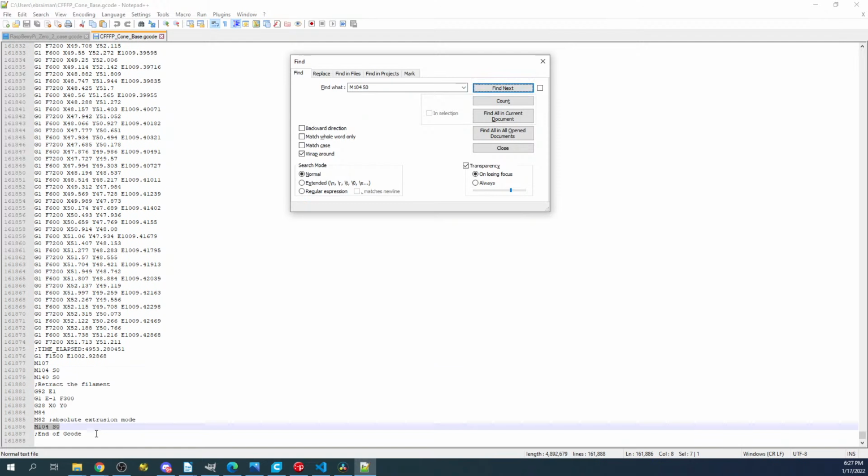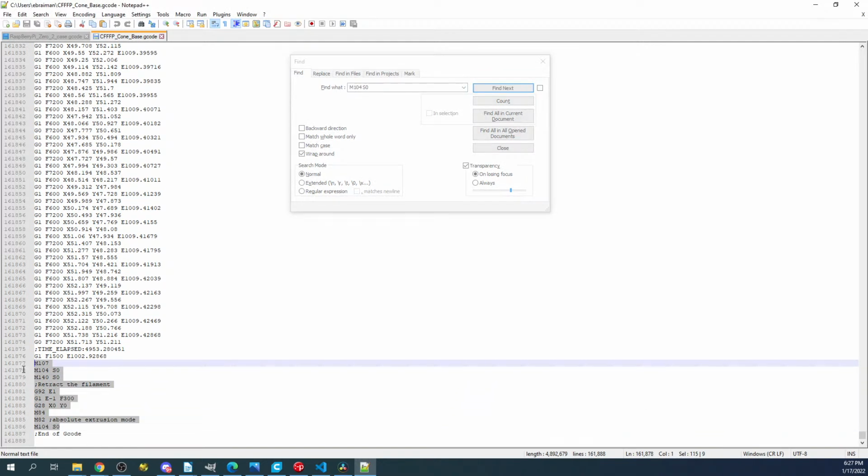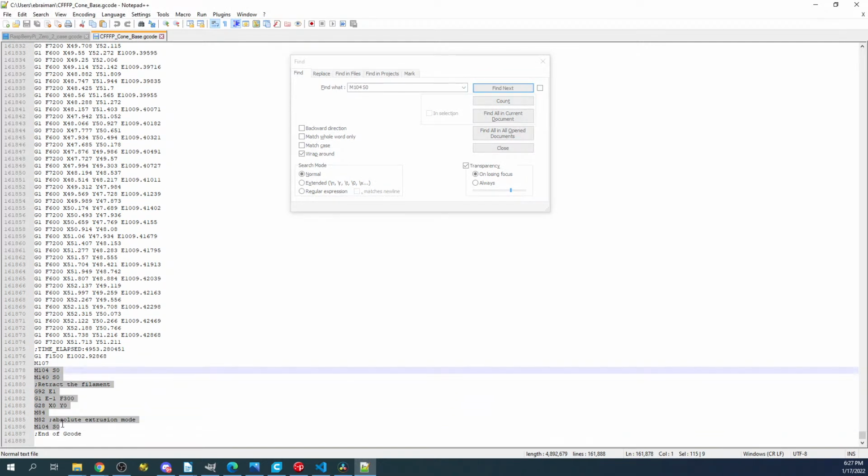So it's turning off 2 right here. Now currently I might not have these marked right. But essentially what's going to occur is when it finishes a layer, when it's multiple actual colors, there's going to be an extra one here when you're using a single extruder that's going to confuse it. And this might have been fixed as a bug, but what you have to do is delete the second to last one. And I'll show you what the extruder looks like that's causing this issue.